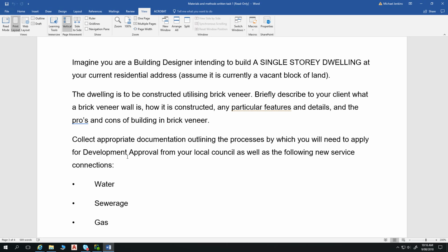Within our concrete, our slab, this is what we call our beam. This section here. So this top piece, let's say that's 100 mil, pretty typical. That top 100 mil slab of concrete is attached to beams. Now we have beams that run all the way around the edge, so edge beams, and then we almost always have internal beams for a residential slab.